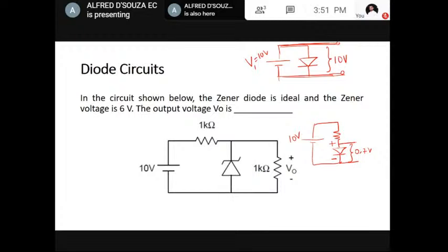But if you do not have any resistor here, then the voltage across the diode is the same as the voltage of the independent source. But here the diode can maintain its forward drop voltage. It has that flexibility. Why? Because the independent voltage source is not directly connected in parallel to the circuit. The same thing happens with the Zener diode as well. Please keep this in mind.